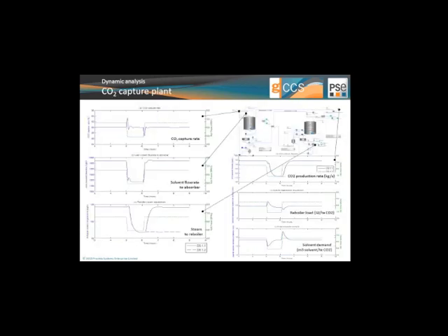And this is actually what we can appreciate in the next set of results concerning the capture plant. We can see here basically the steam, the capture rate moving up, retaining the plant capturing more CO2 than they actually want. We have set up control systems here that would ensure that the capture rate is met at 90%.